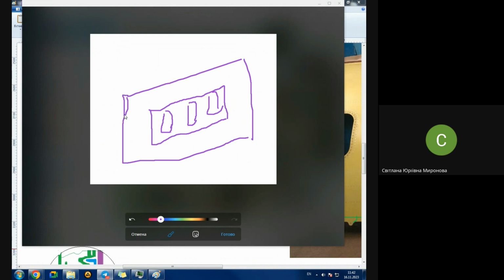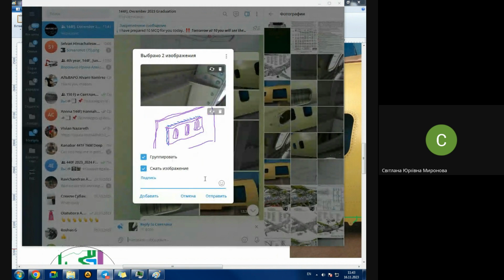So here is skin with some thickness, and in this place they have an additional sheet of material, so the thickness is twice greater. And around them, they use sealant to smooth this place, to cover this place, in case they have gaps there between two skins. Now it's covered with sealant. We see exactly this place in the photo.